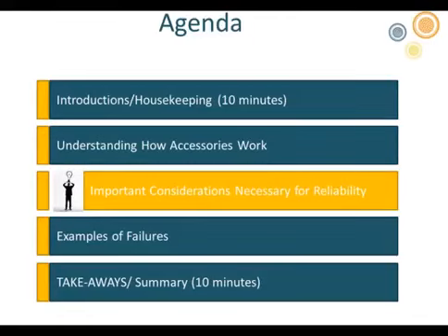And typically we have quite a bit of tolerance in there, usually probably 1/4 to 1/2 inch of tolerance. We don't tell linemen that. We want them to hit it exactly, so that if they are off a little bit, you still don't have an issue.